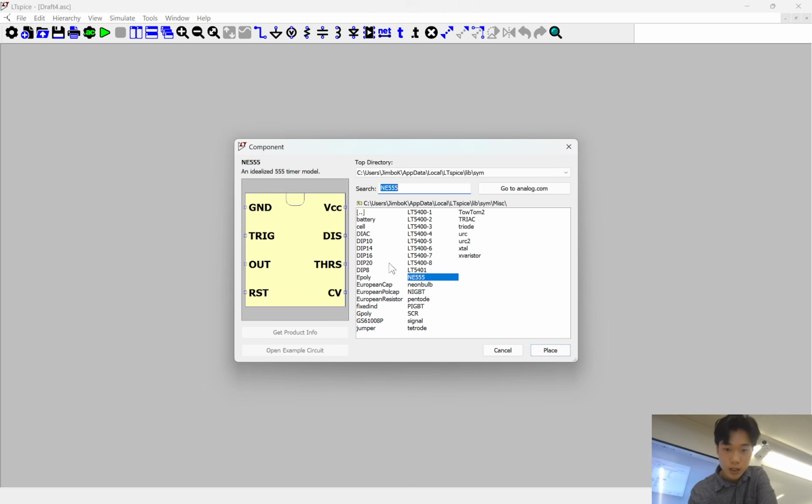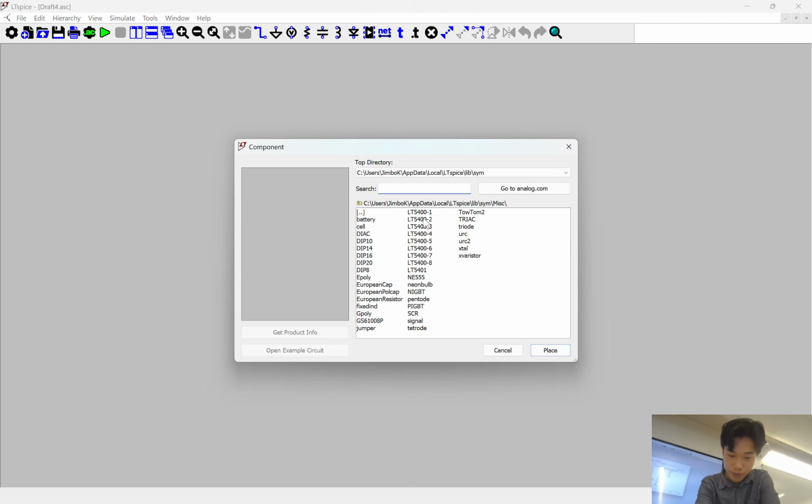Now, so far, most of the uses for op-amps have just been using negative feedback. In this case, we're not actually going to use the feedback at all. So the idea here is, I'm going to take some op-amp. There are actually a lot of op-amps in LT-Spice. The reason for that is because in real life, different op-amps have different characteristics. And not only that, there are some imperfections in op-amps that are not necessarily ideal.